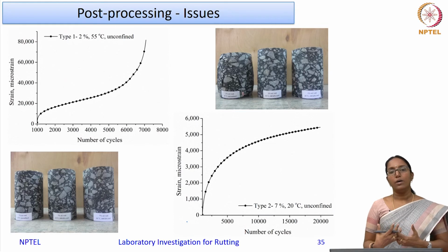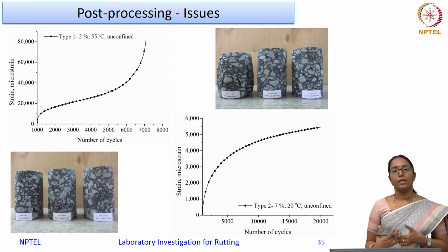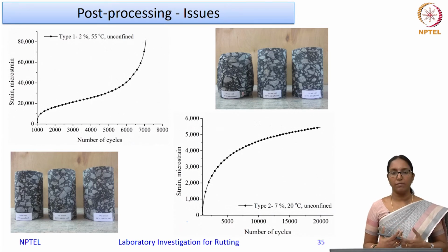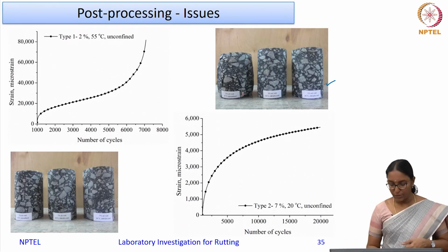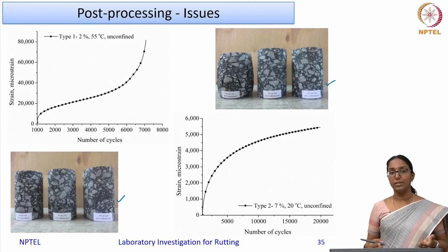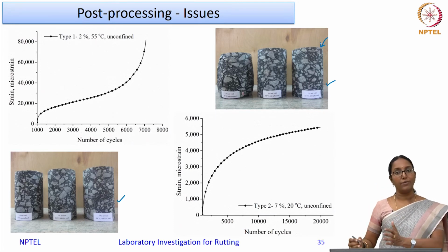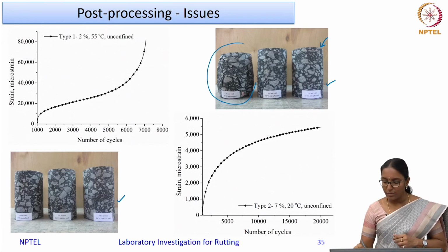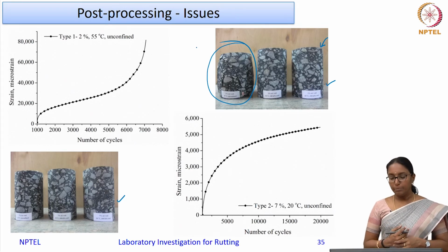So, we have collected a lot of information at IIT Madras to look at this three-stage behavior of mixtures. These are some of the samples that we have used for testing, and these are the samples after their testing. You can see that some of the samples are intact even after the test duration, whereas some have failed by excessive tertiary deformation. As you can see here, it has bulged out and failed.